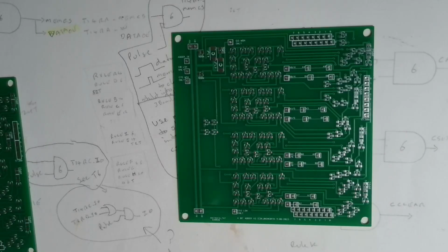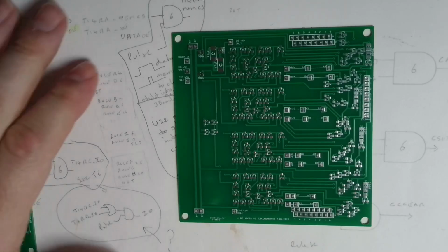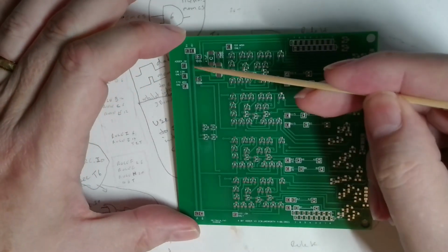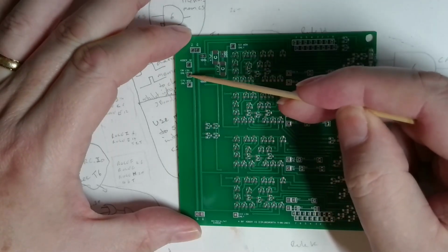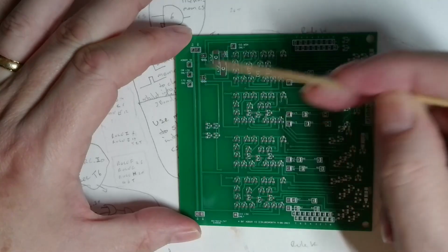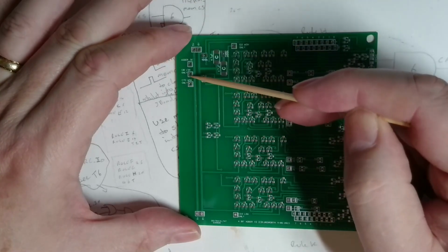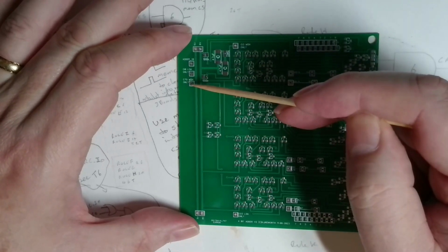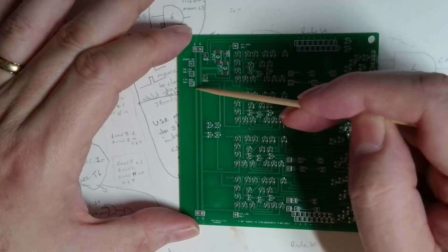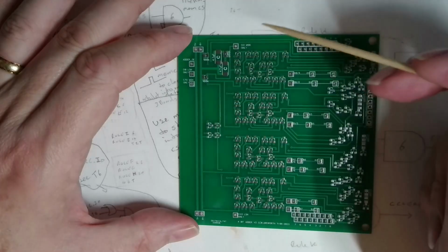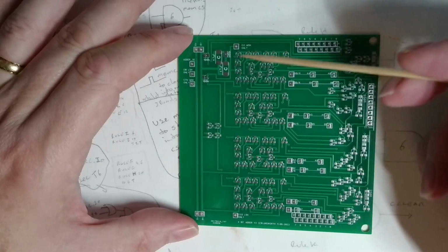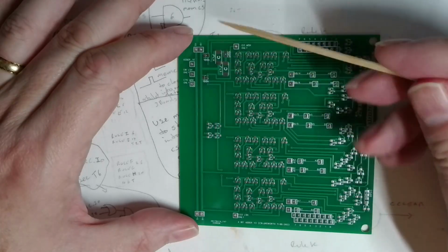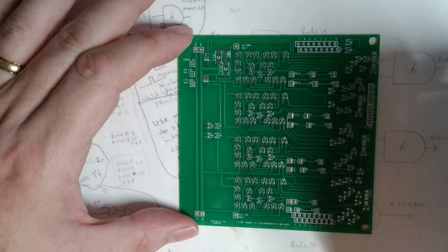Right, here we have the bare board for the one nibble of the adder. So over here we've got the adder output enable, the C input, 0 input, that's the carry or the C register input for bit 0. Here we've got the C7 output, so that's the 7th bit that comes out of there. It won't actually come out of this board, it'll come out of the second one. So carry comes in here. This is active all the time, so whatever's coming in is being added up. We only control the actual output.